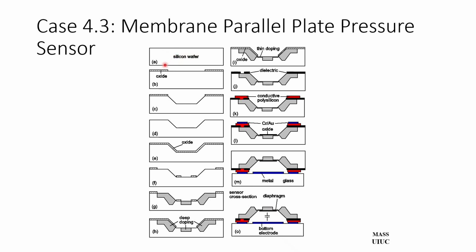We start with silicon wafer, grow oxide as a mask window, then etch this to form a cavity of desired depths. The oxide is removed and then regrown again so that oxide covers both the top and bottom of the cavity. We use photolithography to pattern the oxide. Now keep in mind that the oxide or resist spin coating on the bottom of the cavity is not going to be easy, and the focal depths on top and in the bottom of the cavity are not the same.